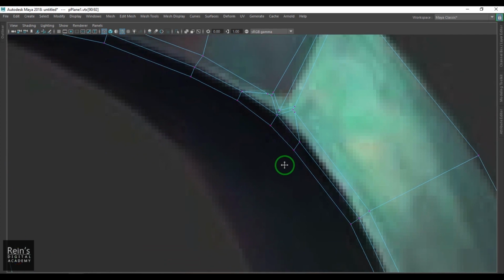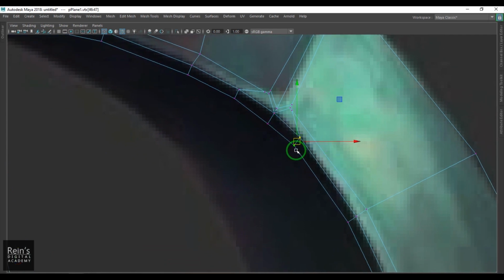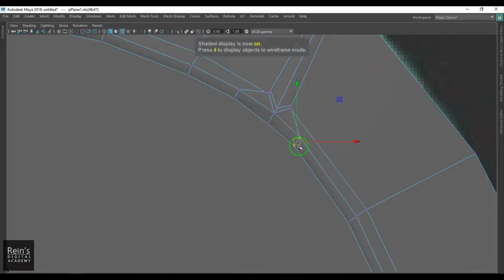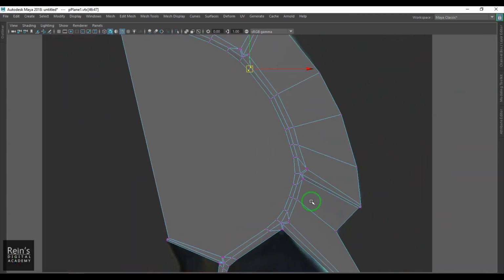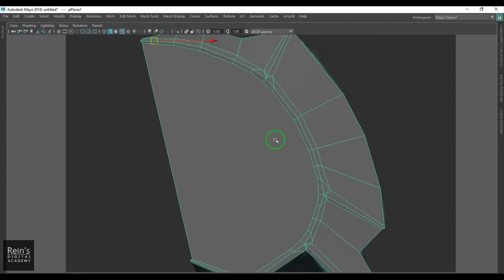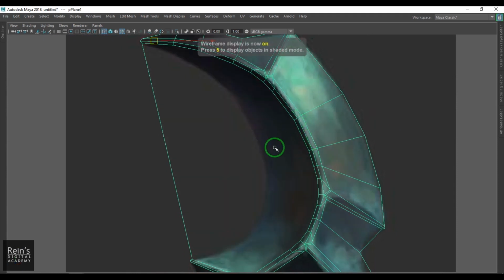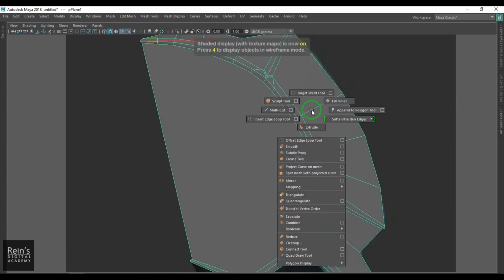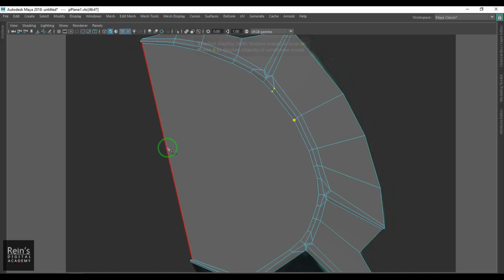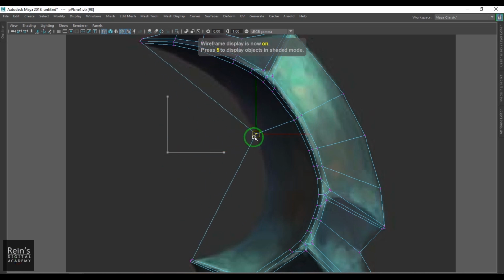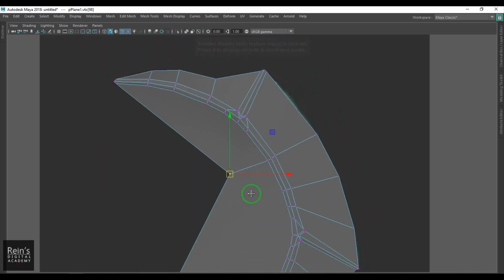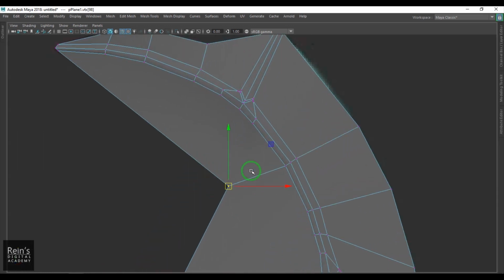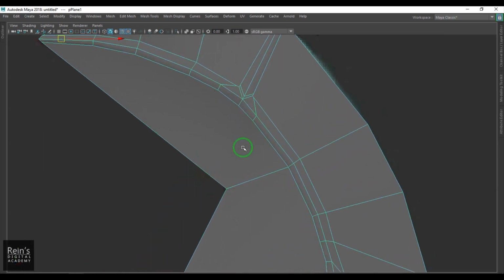Mostly I'm trying to see that it's round. Okay, now I should be able to see there are so many lines. I need to connect them. So I select the multi-cut tool, connect it, and then you get a vertex, and then move it to the blade, and all these lines will now define the curvature. So every line should be connected.